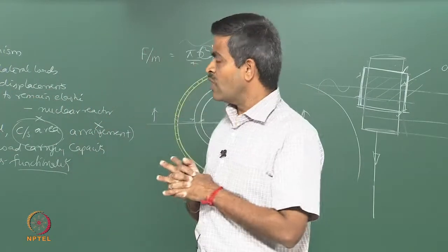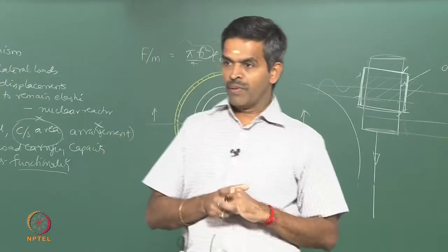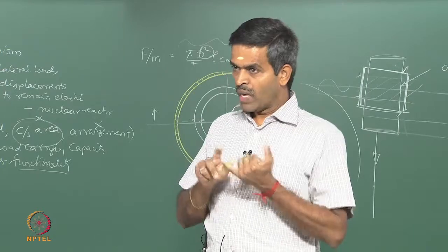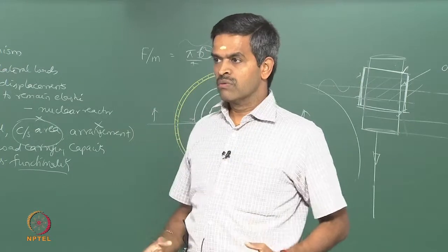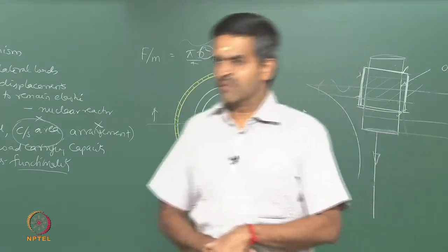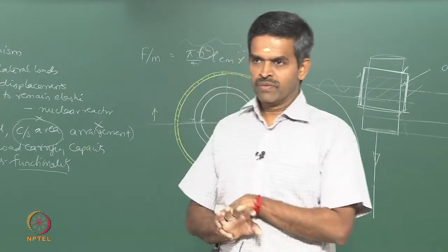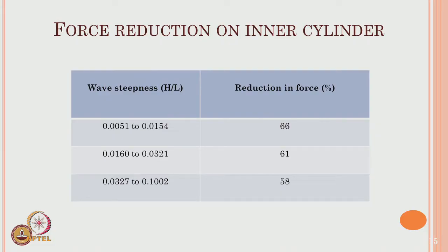One can ask me a question, why 1:1 cannot be done? If you do 1:1, the Reynolds number will be a problem in the analysis. Also, the mesh dimension in CFD goes out of bound, and the computer cannot do the analysis. So, close to 1:10 it was attempted, 1:1 cannot be done for this specific case. It has also been verified that close to 60% reduction is still guaranteed in the given design.